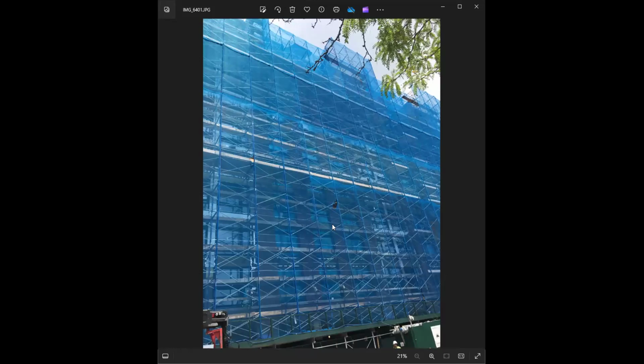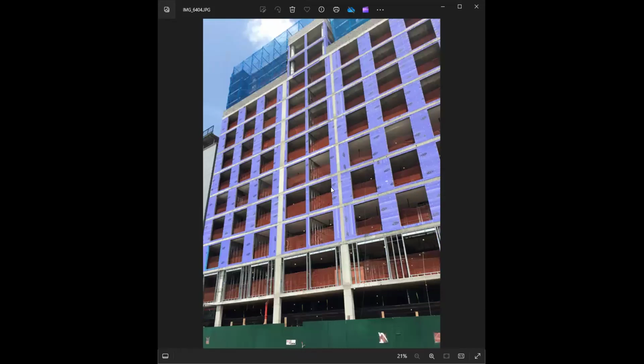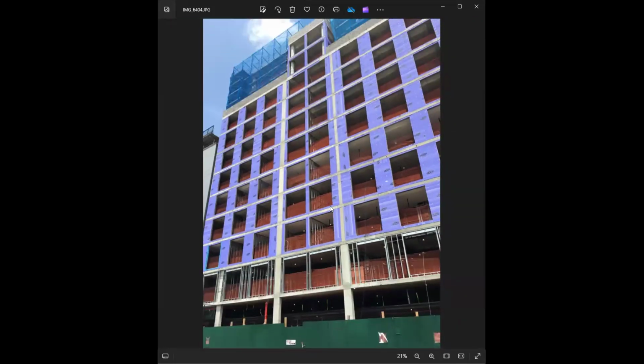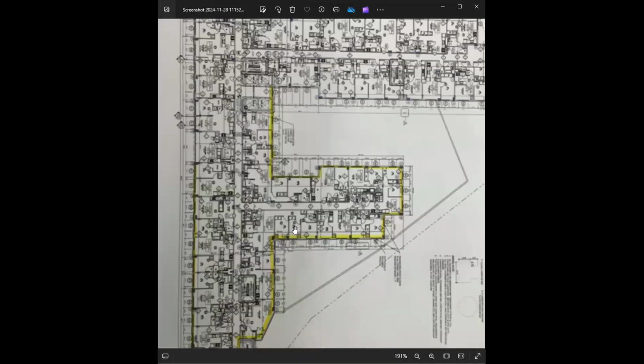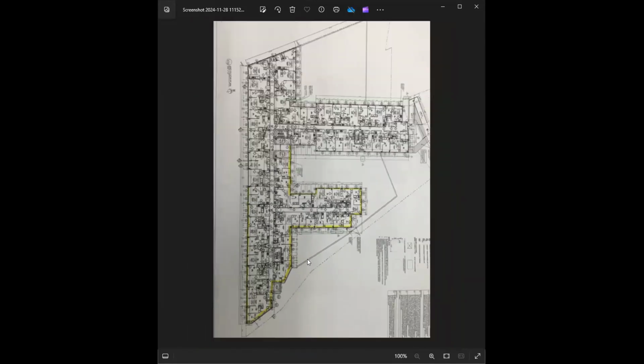Take photos of the part of the building that you have performed the inspection on, so that you can mark on the drawing which part of the building was already inspected, so that your colleague will not do it again, or so that we can close out the job. And this is the final drawing plan. I made some highlights right here where I did my inspection on the day that I performed it.